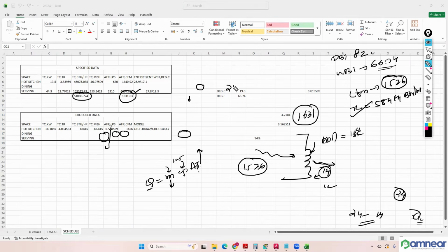For 24 degrees Celsius and 50% relative humidity, the room ADP is 13 degrees Celsius only. But since the coil surface temperature is decreasing due to the mass flow rate reduction, delta T will increase and coil surface temperature will decrease. So instead of 13 or 12.5, sometimes the coil surface temperature will go to 11 degrees Celsius. If the coil ADP is decreasing, excess condensation will happen.